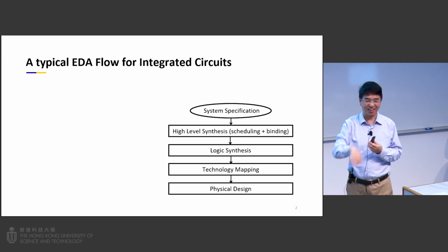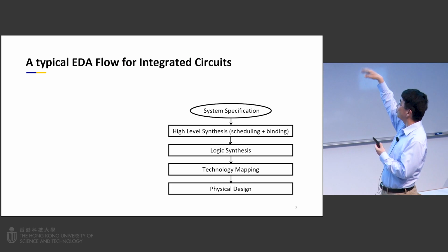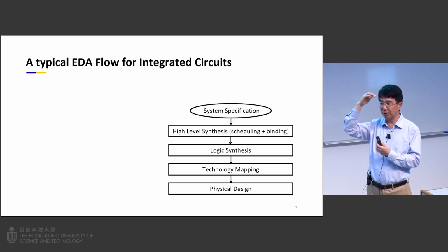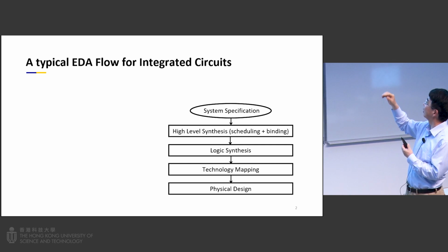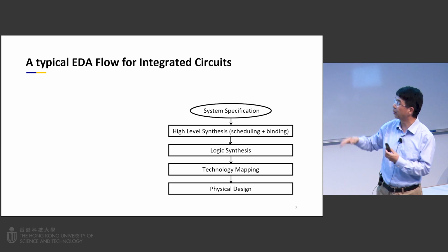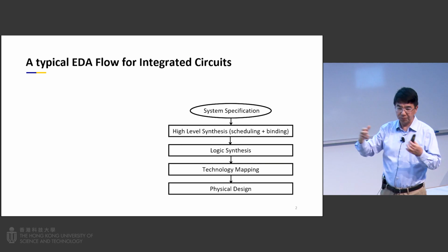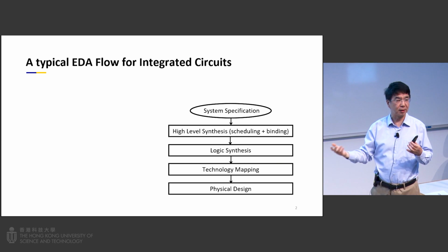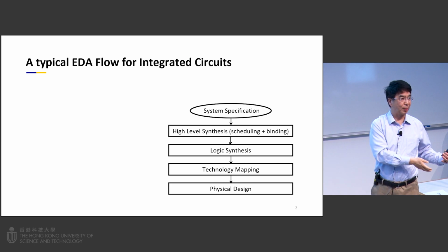High-level synthesis, thank you. These two are two extremes of the whole design flow. First you do scheduling, resource allocation, resource binding. At that time, you already decided which operation happened in which clock cycle, where. And then you synthesize that circuit, you optimize, you map it to a particular library, right? For FPGAs, you map it to lookup tables.